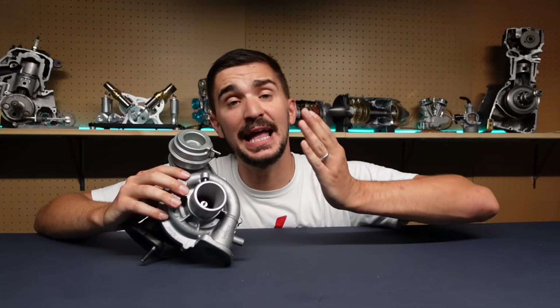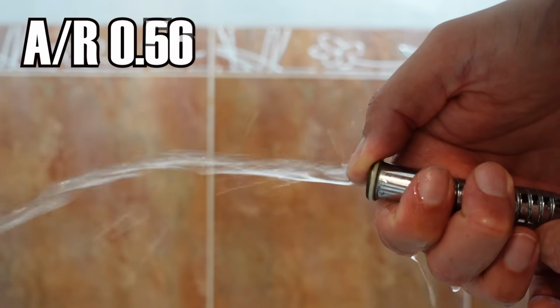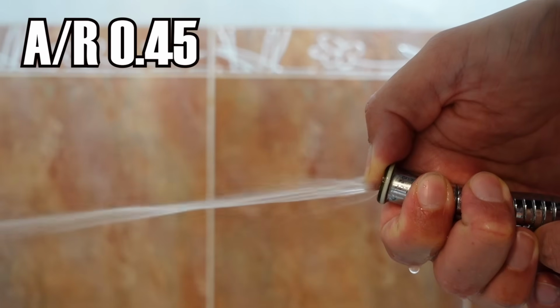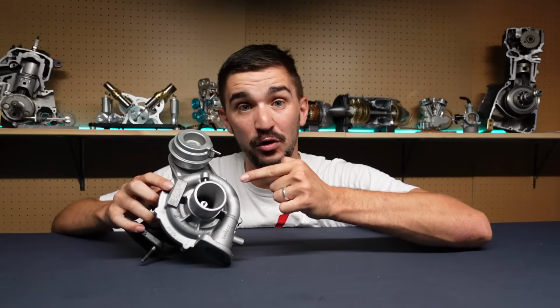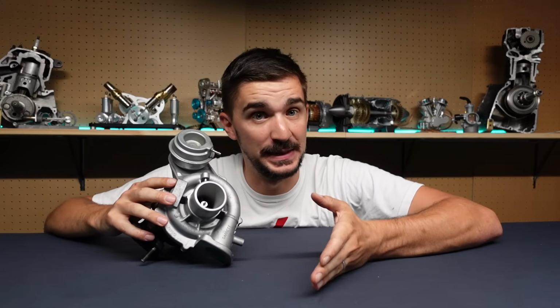To understand what A over R numbers mean in terms of performance, all you have to do is think of your thumb blocking off some sort of hose. The more you block it off, the faster and with greater pressure the fluid comes out, which means that we are enabling a higher gas velocity. The higher the gas velocity, the better the turbo spool up, which means that small A over R numbers improve engine responsiveness and turbo spool up at low RPM.